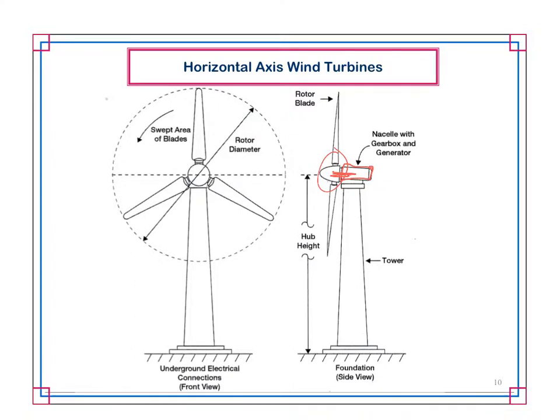So whatever the radius of the rotor is, you just double it, and that essentially gets you this diameter. Inside this area here, this is your windswept area. That's your pi r squared. That's where you're going to actually be extracting power from the wind. Your electricals all come down inside the tower and go out underground. And if you haven't thought about it, you have to have electricity coming out of there. And you don't want wires tacked onto the side of your turbine going out, mainly because you've got blades spinning and you don't know where those directions are going to be.